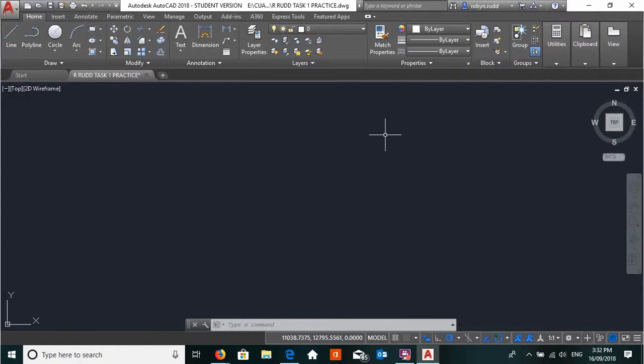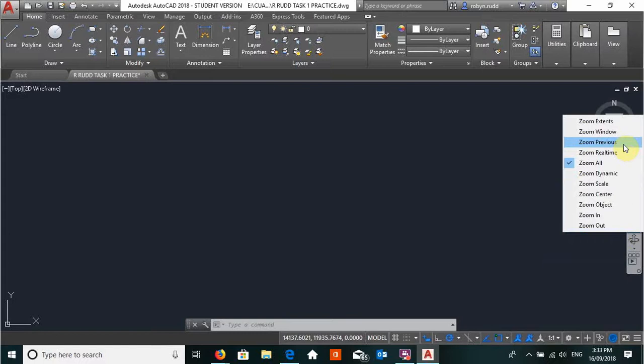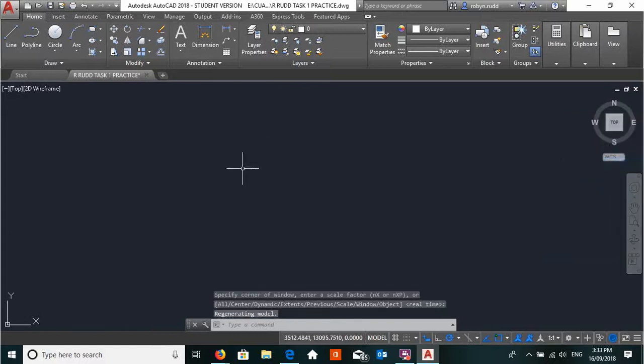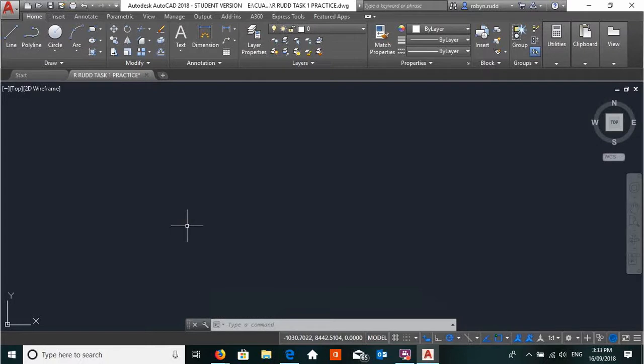It's like a window into this infinity that you're going to be working in. So if I want to draw down here and I want to draw up there and there and there, and I don't know where that drawing is, but I want to find it, then I just type zoom, all, and it zooms everything in, which is great. So that's just setting my limitations, so you can actually see that I'm within a certain area here.